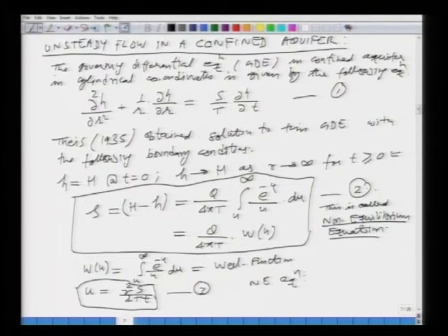Okay. Now, this well function W is something which is very difficult to obtain. This W is a very complicated mathematical function which involves integration of e to the minus u over u du, which is not easy to obtain, and many people have proposed certain approximate expressions or the Taylor series expansion of this W(u), and this is available actually in standard tables. So, it is very difficult to find out the analytical value or the final solution. However, certain tables or the standard tables are available.